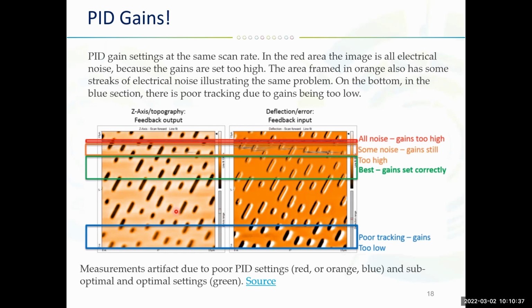So the set point itself affects the interaction force between probe and sample, and a set point close to the parameter value, like outside the contact, is the most gentle for the sample itself, but it slows down the feedback control. Do you have any questions about the gains? If not, then I would like to go on to